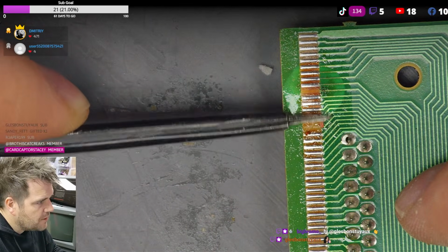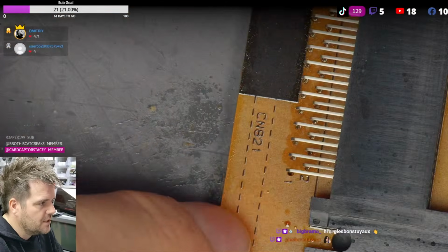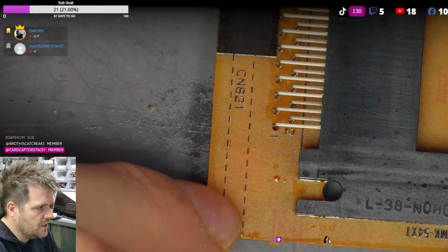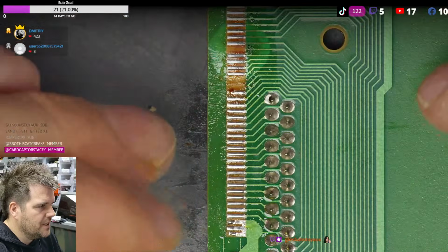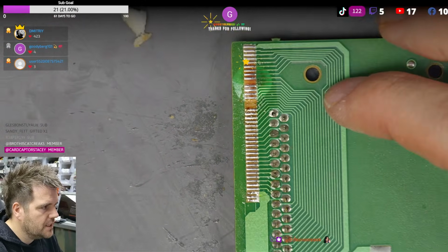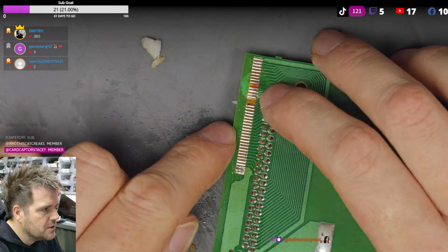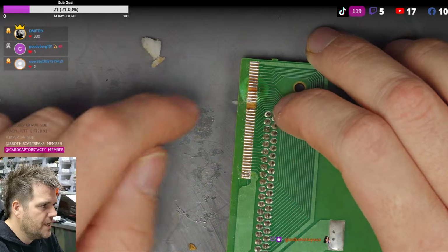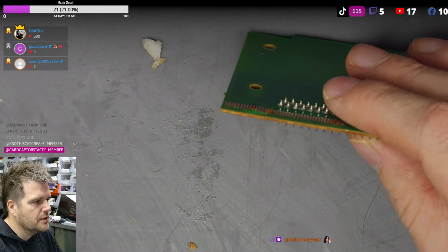And it would be nice to probably just remake this PCB, because you can see it's a single layer PCB, that's also another reason why it's so weak. Lift this connector off and just remake this little PCB and have the connector already on here. So that'd be a nice thing to do. So let's just clear that up. You can see it's also already, that's the popcorning I'm on about. That's the part where we use the soldering iron, and this is what I'm on about all the time with boards where they can popcorn.